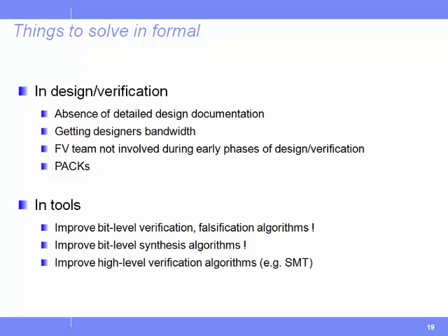One is the cone of influence, which is very simple to catch, with structural traversal and all that. They also want to have stuck-at 0 or 1. They also want some signals that will be stuck at 1 or 0 after some time, let's say after 10 clock cycles. So that is the kind of information they want. Like some logic is unobservable, so they want to have that.